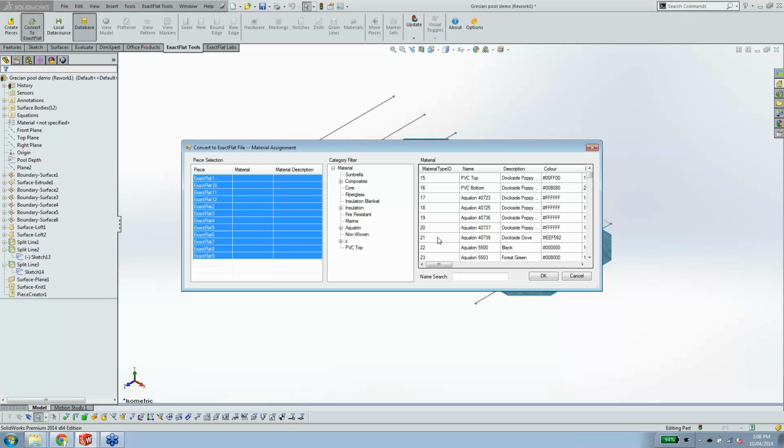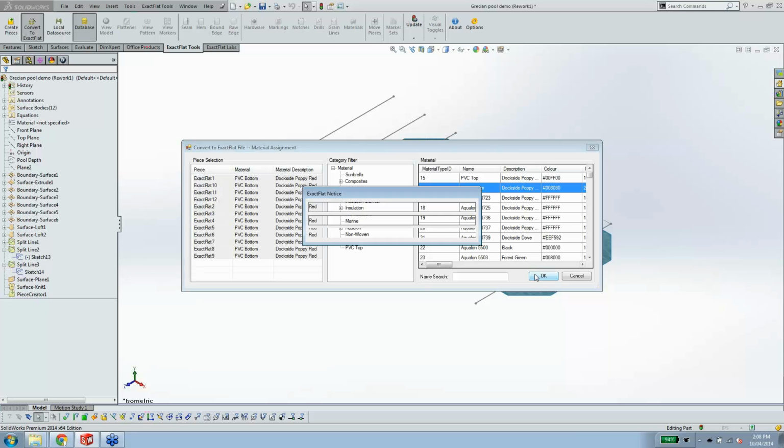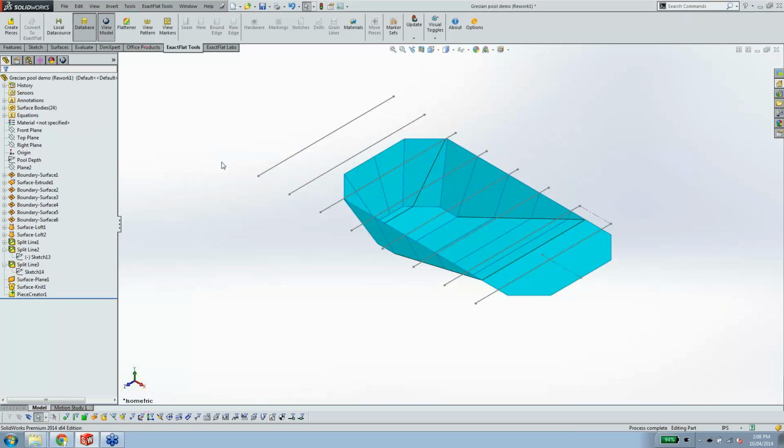So for example, if you've got a particular pattern design on the bottom, which is different from the pattern design on the top with sort of trim coping tile or something like that in the top, you could do either one of those. If you had a 5 mil, or say a 7.5 mil, or say a 3.5 mil thickness, you could assign any type of material to whatever aspect you wanted to assign here. So let's just go ahead and pick the PVC for the bottom here.